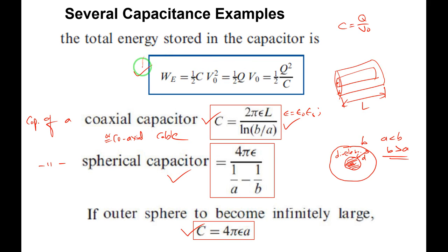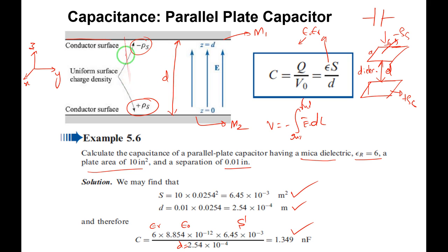We know that the capacitor is capable of storing energy. Why is it capable of storing energy? Between the conductors there is a dielectric material. Whenever a field is applied across the capacitor, dipoles get generated in the dielectric material, meaning it is subjected to polarization. This polarization effect is capable of storing energy, just by the relative shift in the positions of the dipoles. Hence we say that the capacitor can store energy in the form of field in the dielectric medium.